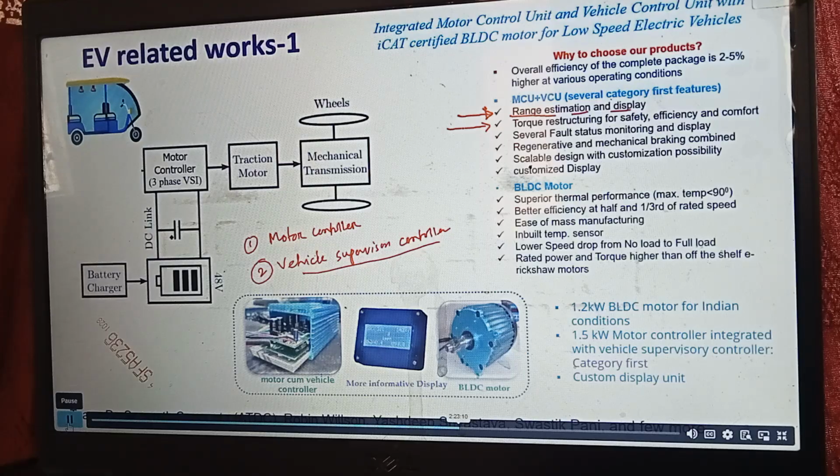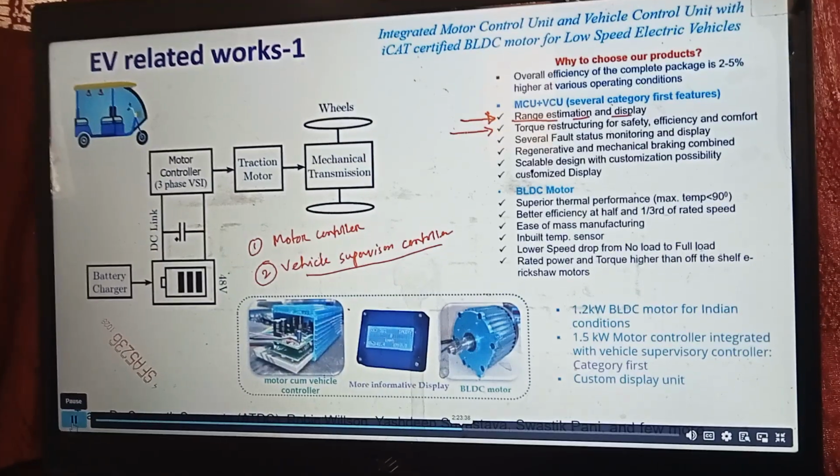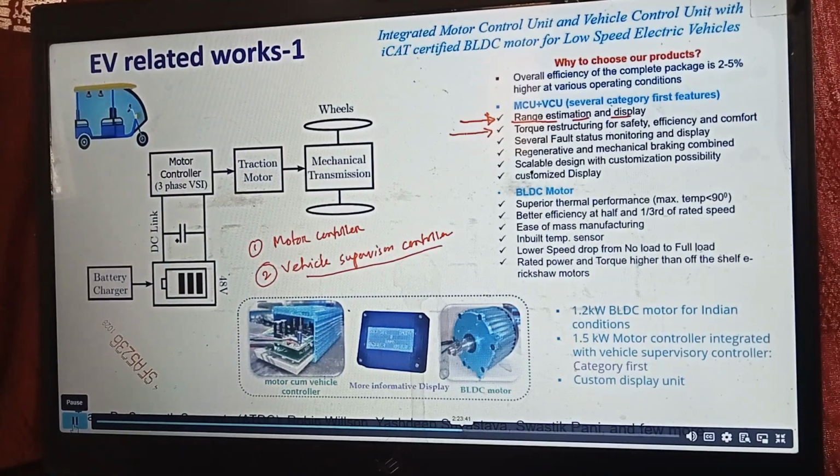in this kind of vehicle, sometimes people do overload. It is actually designed for, let's say, 4 passengers and 1 driver, but they keep on having more people. And these vehicles are designed for certain gradability, but sometimes people try to extend, they try to go on higher slopes, right? So if you do not protect your motor and motor controller, due to this overloading, it can get damaged, right? So we incorporated a protection in our system.